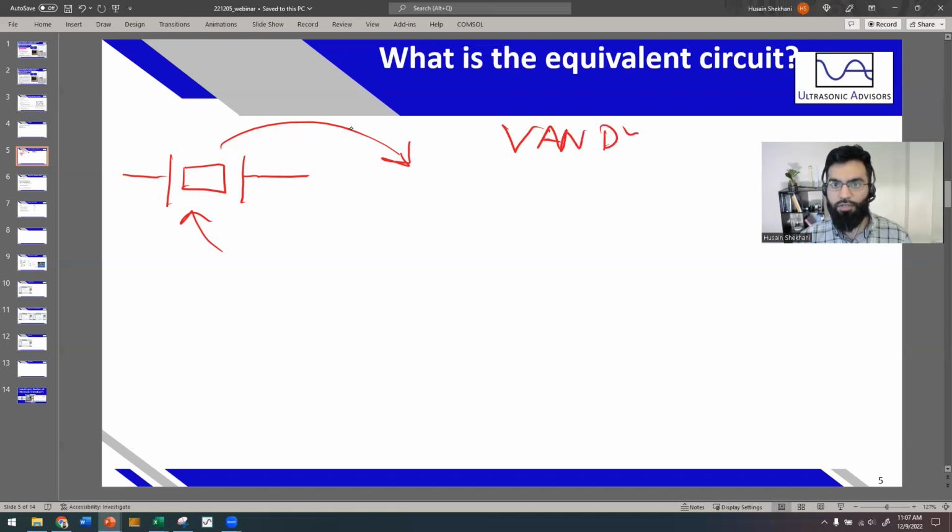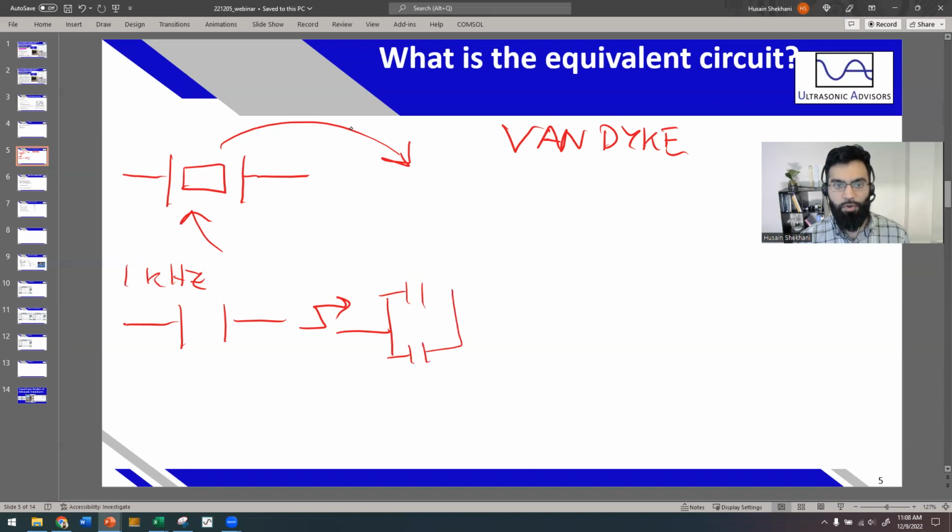If you remember from last time, we talked about the capacitor model, off resonance, let's say at 1 kilohertz for an ultrasonic transducer. Your piezo element is a capacitor, but I said, hold on, you can actually split that up into two capacitors, one representing your mechanical branch or your mechanical energy.